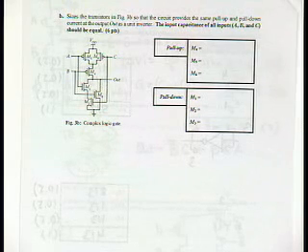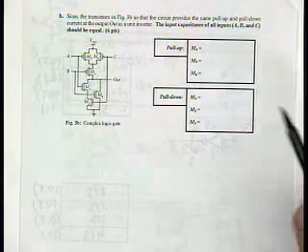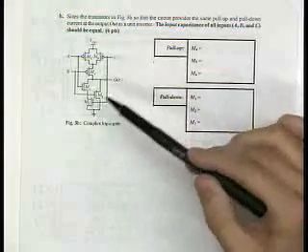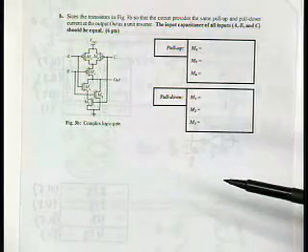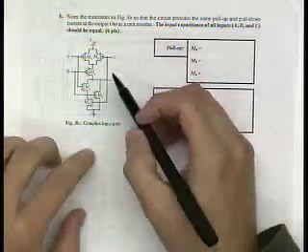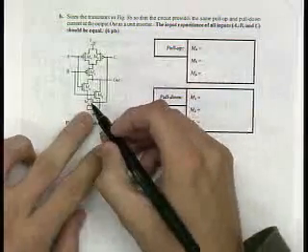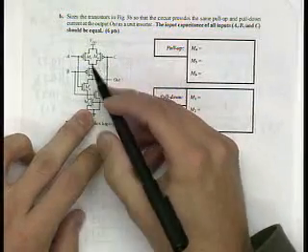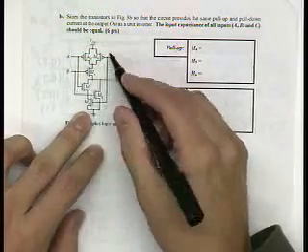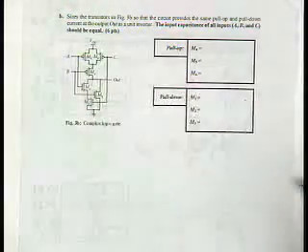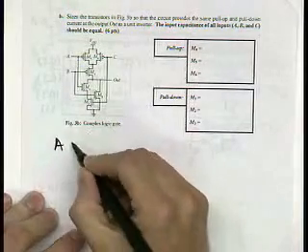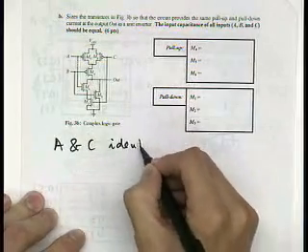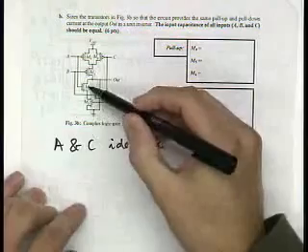So what we have to observe here is a couple of things. First, the problem asks you to figure out the logical effort for this logic gate under the assumption that input capacitances are equal. By inspection of this circuit, M2 is connected to M6, M1 is connected to M5, and this is input C, this is input A. Since input capacitances have to be equal, A and C are identical.